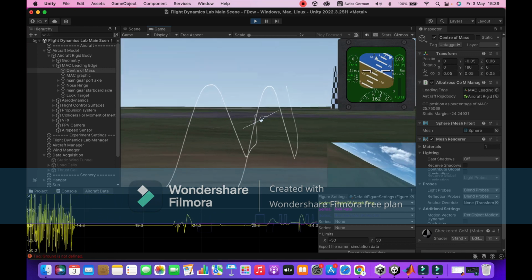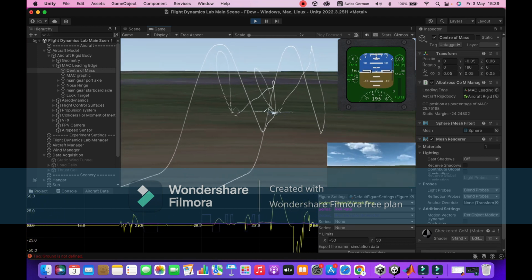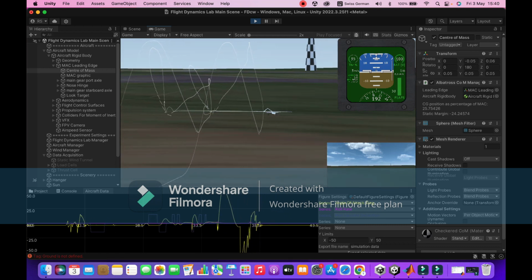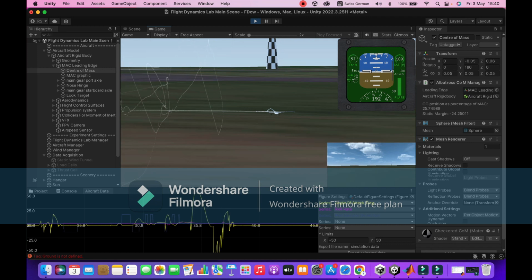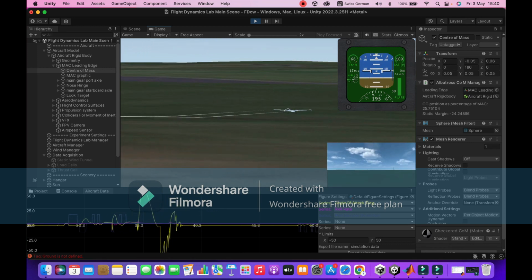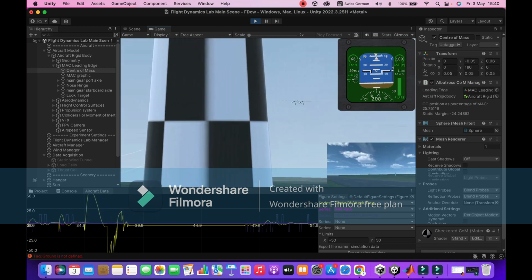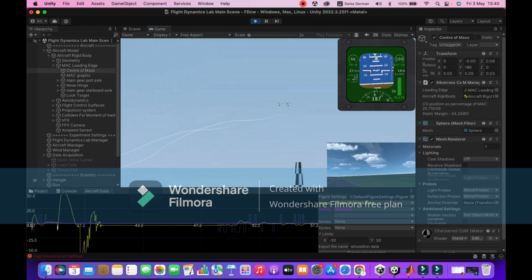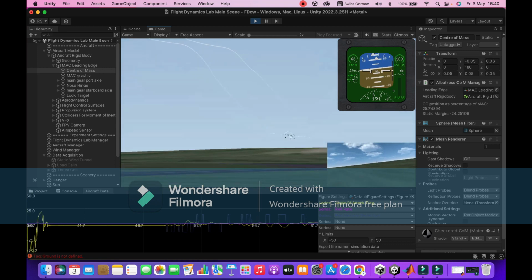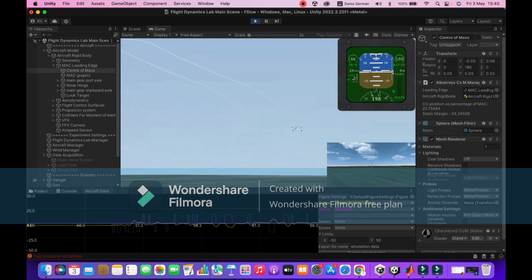So let's try now for flaps down. So flaps down now, increasing the speed to 15. So the takeoff with flaps down is around 15 meters per second, which is a bit less than flaps up. And this is expected because flaps down position increases the lift.